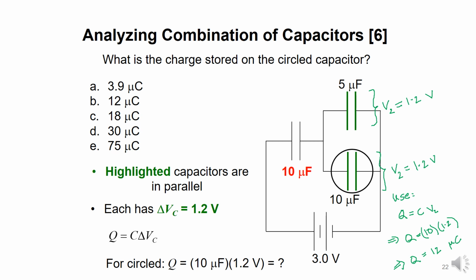Okay, so you can look at the previous few slides, look at the steps involved. We start with the original circuit and then simplify it to get the equivalent capacitance of combination. So we combine 2 capacitors at a time in this problem. So we do it for the red capacitors and the green capacitors. And then once we have the simplified circuits, the red and the green combinations, we combine them to get the equivalent capacitance of the entire system.